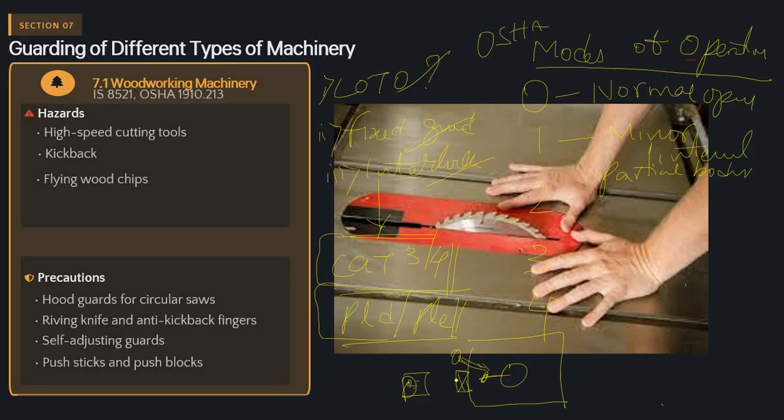There is an adjustable door, and for that an interlock is there. But what kind of interlock? It should not be like a photoelectric one with a reflector. It should be a category 3 or 4. Category 3 or 4 is a high-performance device which has a dual channel safety circuit. If you do not understand, let me know, and I will explain in detail if required.